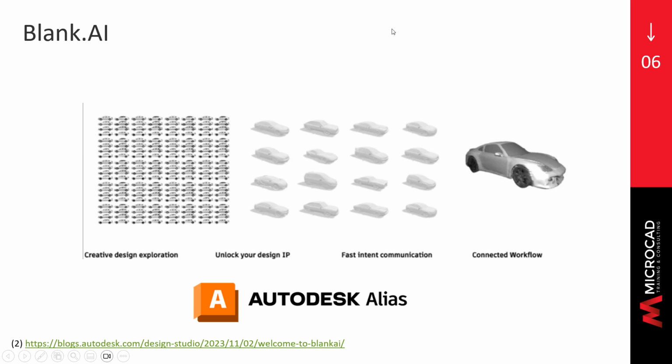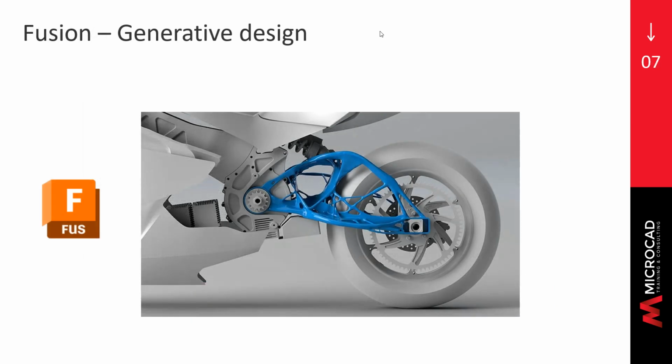This has been done lately in the software with very good results, and it makes the job go faster, more efficient as well. In Fusion, for example, there's a generative design tool as well for basically defining a part that should comply with certain requirements, such as maintaining a load in point A, maintaining a constraint in point B. So basically, you tell the software, you know what, I need this part that's supposed to join this wheel to this crankshaft, and I want to send power from the shaft right here.